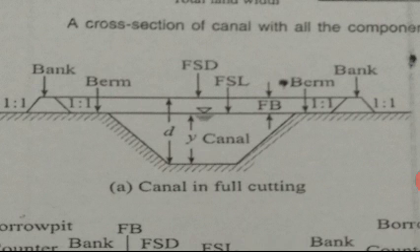Berm is necessary to provide bigger waterway. Berm is necessary to reduce leaks and breaches of banks. Berm is necessary for the provision of borrow pit in future. Berm is necessary to provide additional inspection path. Berm is necessary to provide additional strength to banks and canal section.